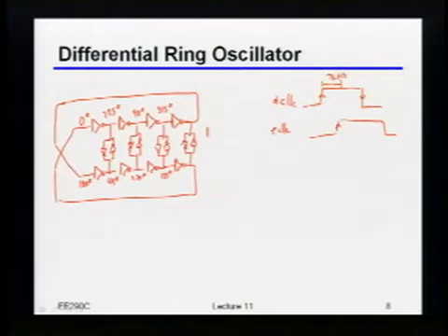If I had a 0 delay inverter, it would be 180. The way I got 45 is that to get through this ring, I have to go through this upper path, ring around here, the lower path, and then come back. So there's 8 of them per clock cycle. That's where the 45 comes from. Okay?